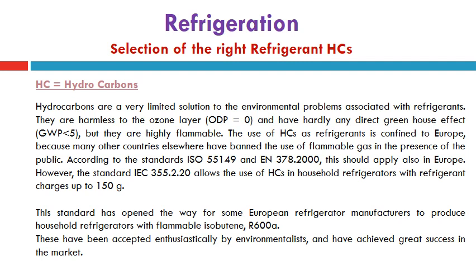The use of hydrocarbons, nomenclature HCs, as refrigerants is confined to Europe because many other countries elsewhere have banned the use of flammable gases in the presence of the public.